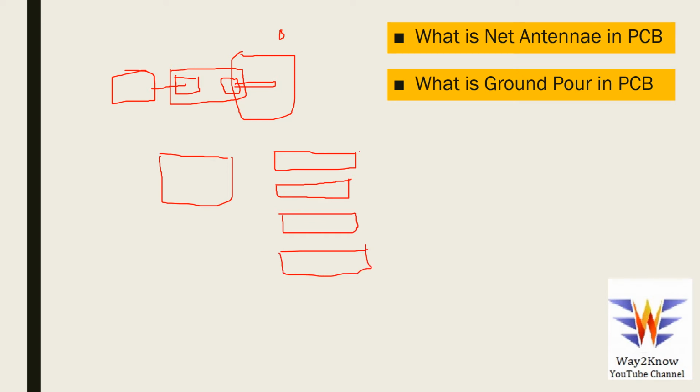So this is a top layer, this is a ground layer, or if you want to use it as a signal layer, you can use it. And let's assume this is a ground layer again, or a signal layer, or a power layer for that case, and then this is again the bottom layer, okay. So top layer, ground, power, and bottom. So this is a reference plane, this is a reference plane.